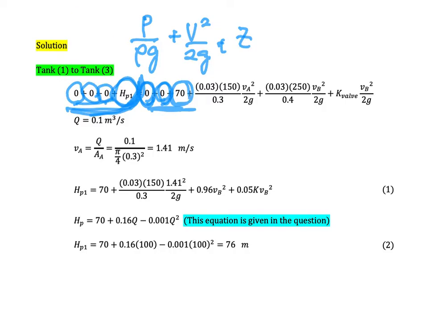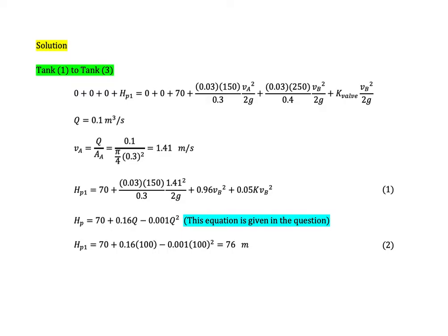And then you could check the Bernoulli equation here by having a simple assumption. For example, according to this equation, we found that energy from the pump will be added into the fluid, into the streamline, into the flow, and then because the flow has more energy, the fluid can go to the upper level.